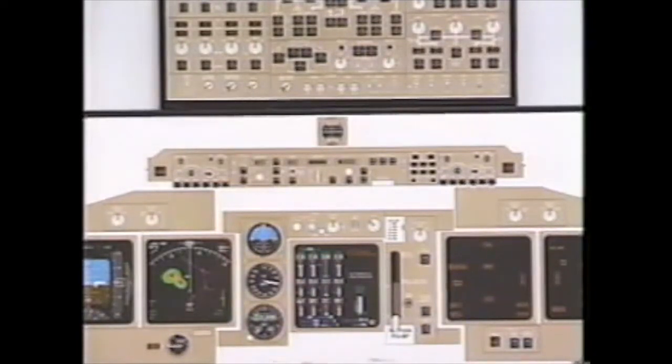Underlined numbers with regards to autopilots. The minimum altitude to engage an autopilot after takeoff is 250 feet AGL. The SOP is to call for it around 800 feet. Minimum altitude to have a single autopilot engage for an ILS approach is 100 feet AGL.